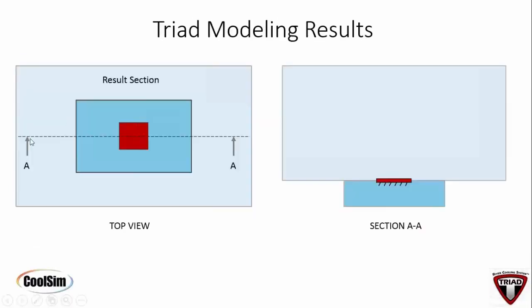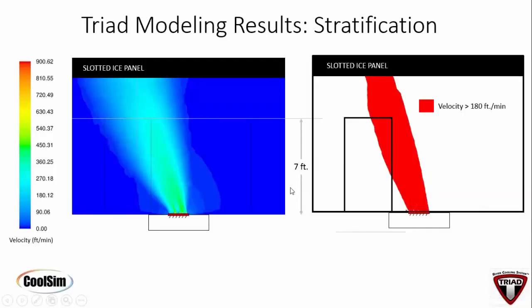And the next thing we started to do is we looked at a cross-section. We sliced in this direction. So here we're looking straight down at the tile. This is a bird's eye view looking down at the floor of our simulated model. And we're taking a cut right straight through it, and we're going to show you that over here. So this shot is sliced halfway through the tile, and we put some simulated racks in place here. So there's an outline of a rack you can see right here, and an outline of a rack here. And we're looking at flow, and in this case we're looking at velocity as, again, a function of color.